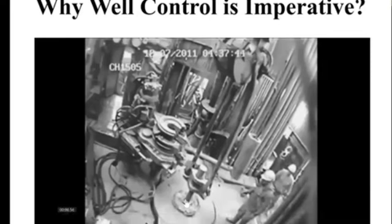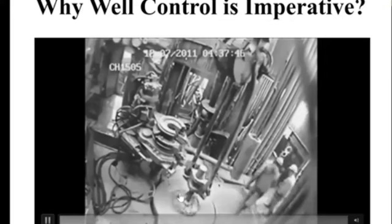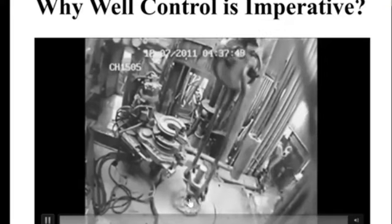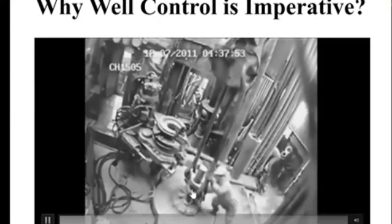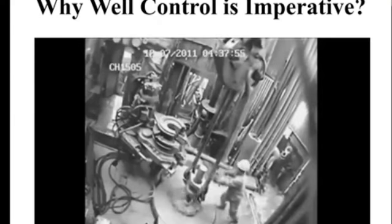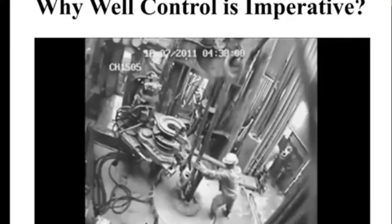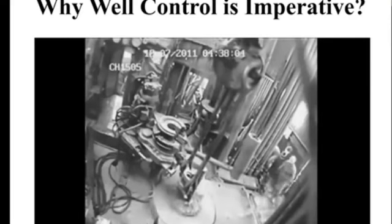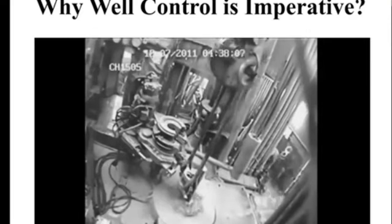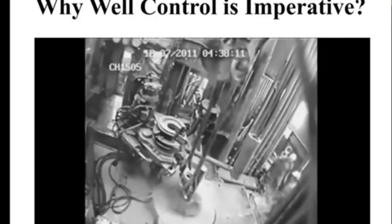Now, as you can see here, the drilling mud is coming out of the wellbore, which is not supposed to, because when we're tripping out, during the tripping out operation, the well must be in static condition, meaning that no formation fluid entering the wellbore, nor drilling mud entering the formation. But here you see that drilling mud is coming out of the wellbore.